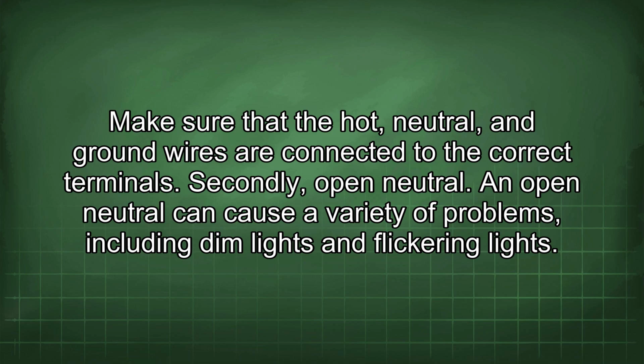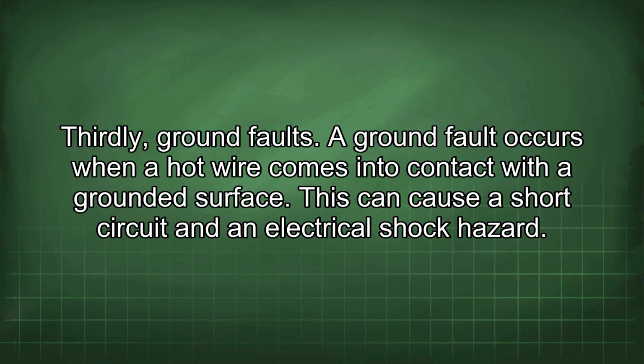Secondly, open neutral. An open neutral can cause a variety of problems, including dim lights and flickering lights. Thirdly, ground faults. A ground fault occurs when a hot wire comes into contact with a grounded surface. This can cause a short circuit and an electrical shock hazard.